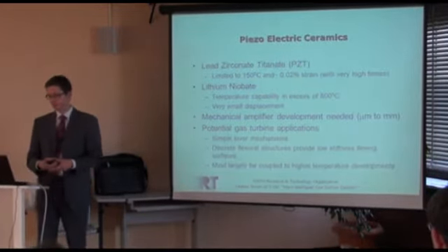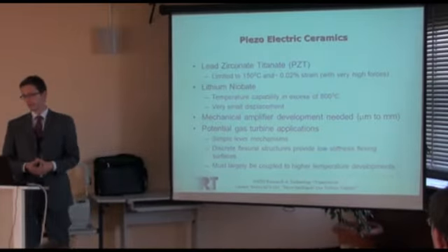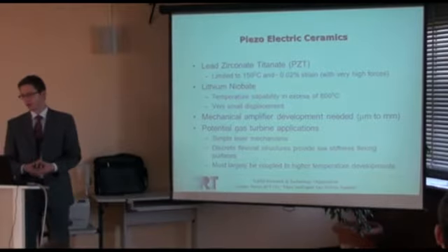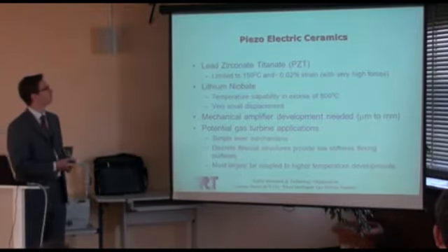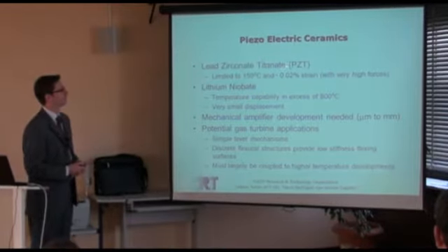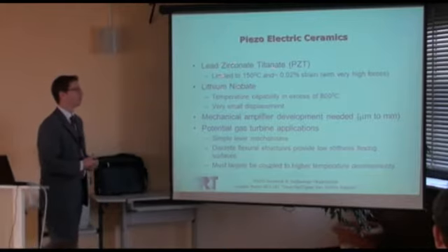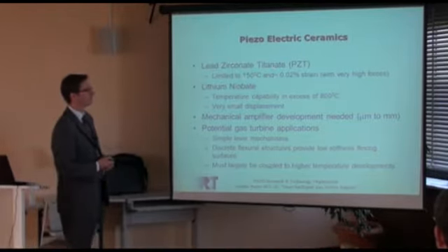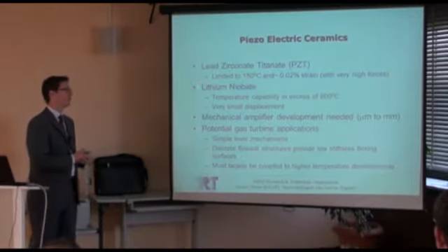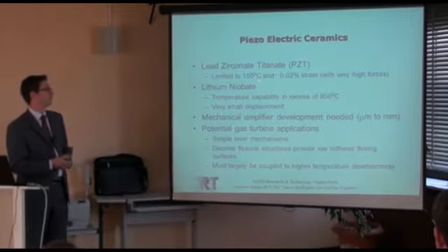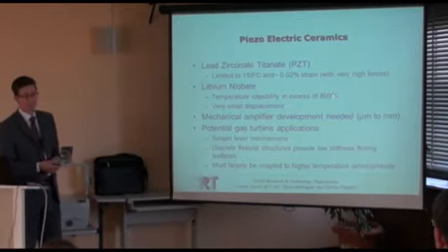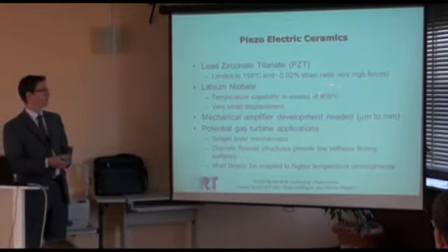Okay, let's go first into the piezoelectric ceramics, piezo elements. They are often made of lead zirconate titanate, but that has a very low temperature limit of 150 degrees Celsius. A better choice is lithium niobate, which has temperature capability up to 800 degrees centigrade.